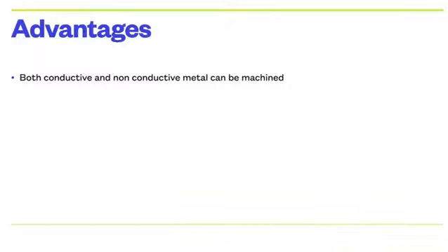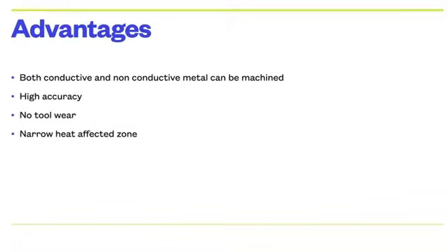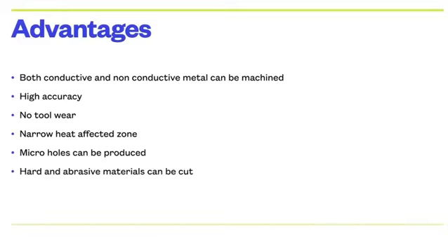Advantages of laser beam machining. Both conductive and non-conductive materials can be cut. It gives high accuracy, with almost no tool wear. It has a narrow heat affected zone. Micro holes can be produced. Hard and abrasive materials can be cut.